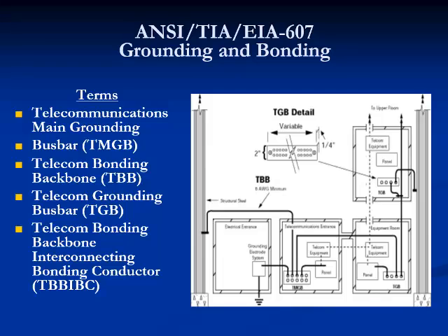The 607 standard specifies a uniform telecommunication grounding and bonding infrastructure that shall be followed within commercial buildings. These systems require a reliable electrical ground reference potential. Grounding by attachment to the nearest piece of iron pipe is no longer satisfactory to provide ground reference for sophisticated active electronics. Solid copper grounding bus bars are installed with insulated standoffs in entrance facilities and equipment rooms, as well as each telecommunication room.